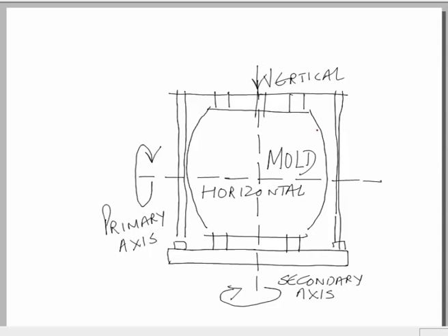So, this mold is also heated. So, we may be using a heated mold. When the raw material is put inside the heated mold, it fuses together with the adjacent pellets, and finally under the rotation this particular material which is present inside the closed split mold is thrown out towards the walls of the mold, and it sticks to the walls of the mold, although we have a non-stick type of coating, so that the final product that we form does not stick to the walls of the mold.